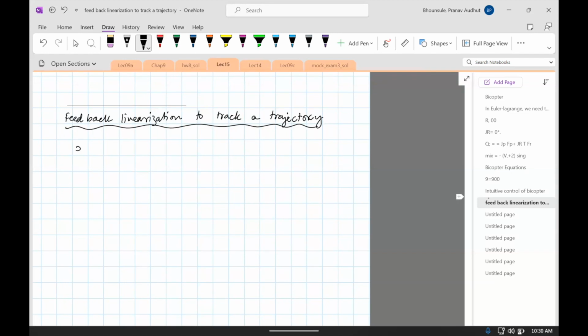So what you do is you set phi ref. Okay, so what's going on here is, first of all, there is a trajectory, and I'm interested in the lemniscate. This has a certain x ref, y ref, x dot ref, y dot ref, x double dot ref, y double dot ref, indicating the reference for the x and y position. Now I don't care about the orientation of the drone. That is a free variable. It doesn't have to be at a specific location.